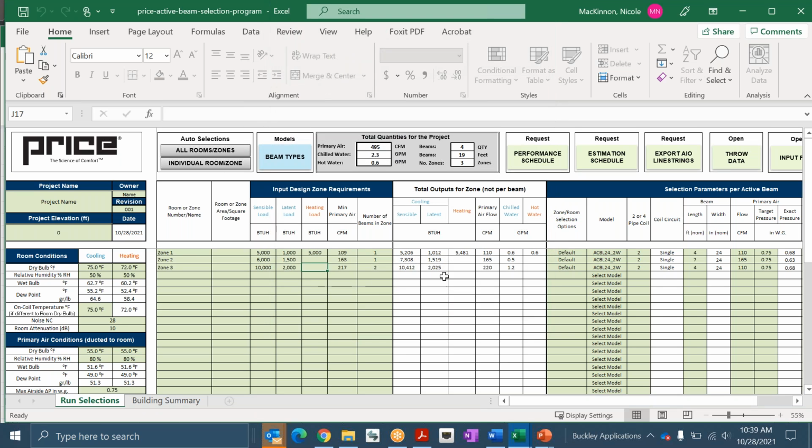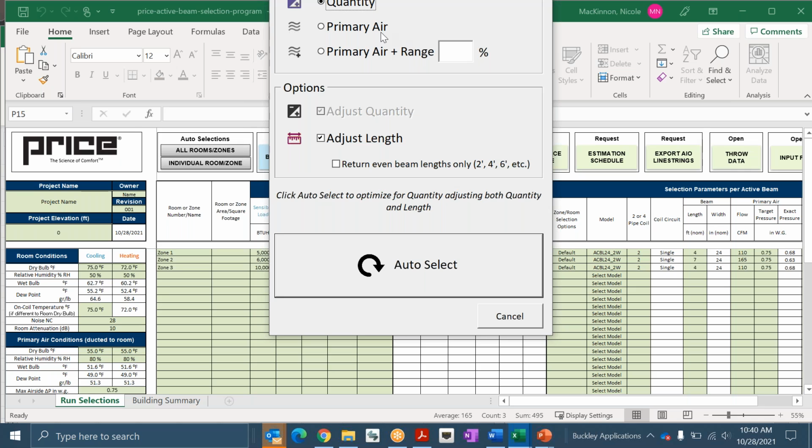And we're just doing this one line, the third line. I've got a solution, and it's basically the same thing in this scenario. But we have a pretty accurate selection already. So let's go back and try this again and see if I can get that CFM a little bit lower. So maybe in this case, I'm at 500 CFM, but maybe my air handler is a retrofit, and I've got an air handler sized for 400.